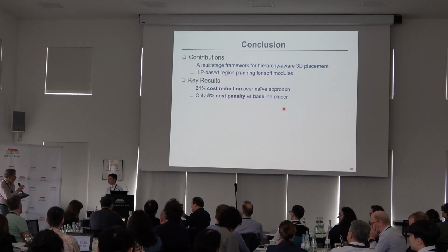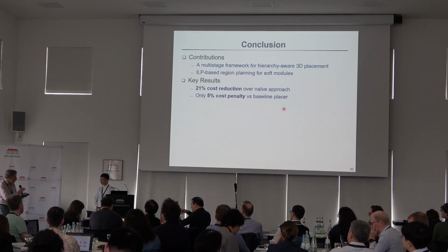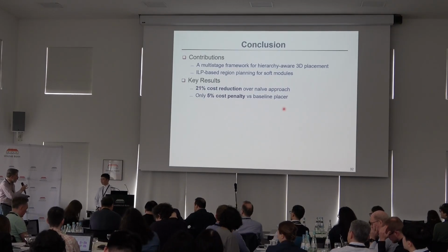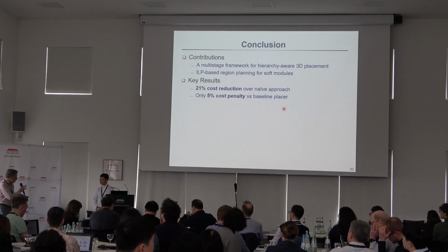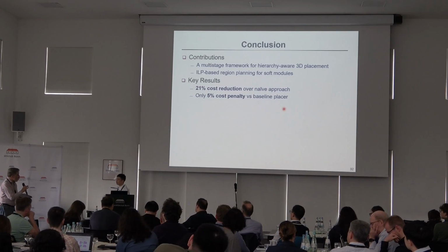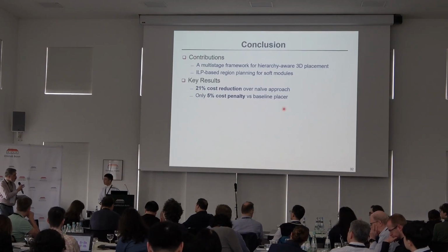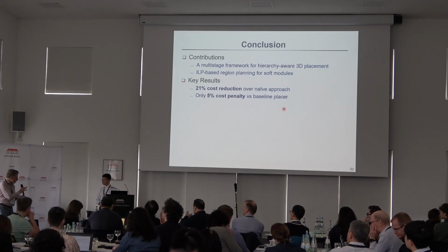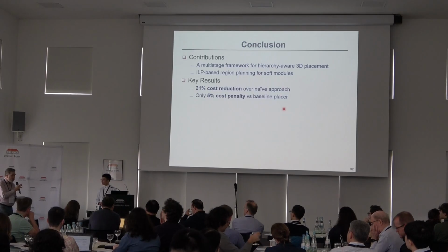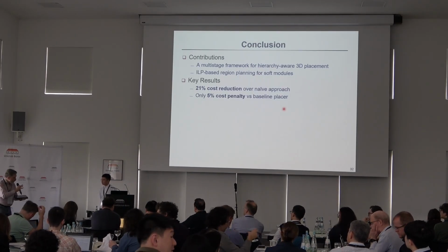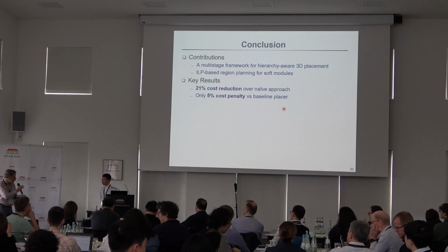So when you use K-hyper, you're trying to minimize the number of connections between layers. Do you have any sort of distribution of the interlayer connectivity, how balanced is it, is I guess my question. You mean how to shorten the interconnection between tiers? Right, and are the connections between tiers uniformly distributed across the core, or are there areas where you might have more dense interconnections than other areas? It's basically a TSV question of where can you make connections, and how do you balance them across the two tiers?